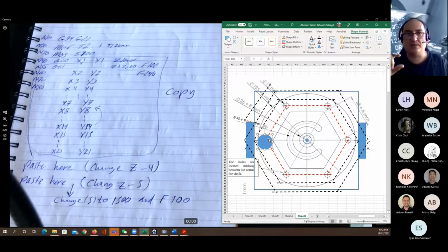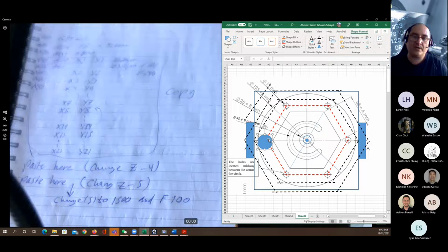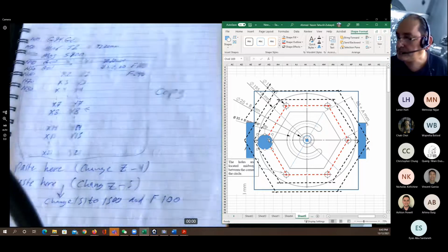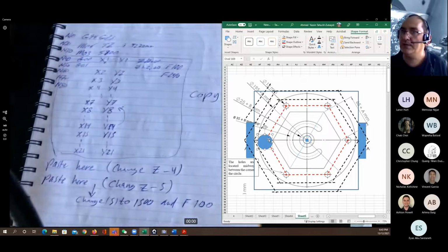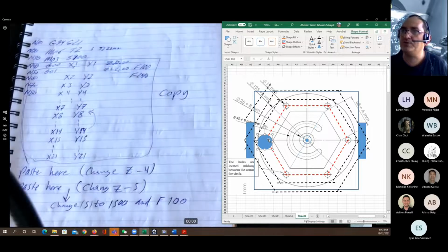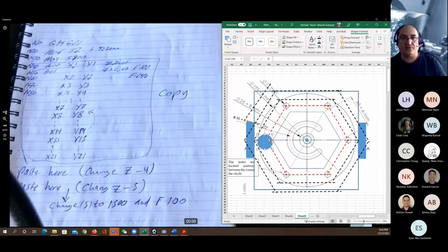So you will say that I would like to repeat the following steps 3 times, as Z equal to -2, Z equal to -4, and Z equal to -1. The machine, which is a computer, will understand that we need to cut it in 3 steps, 2 rough and 1 finishing. We can learn this one later as we go. Usually this is not preferable to be learned in the manual handwritten.